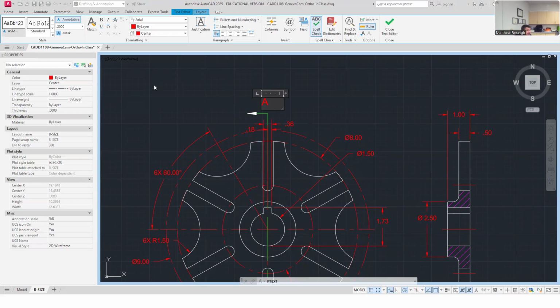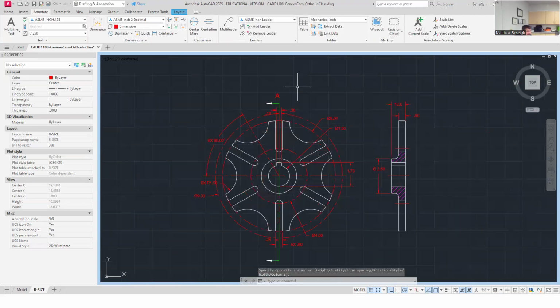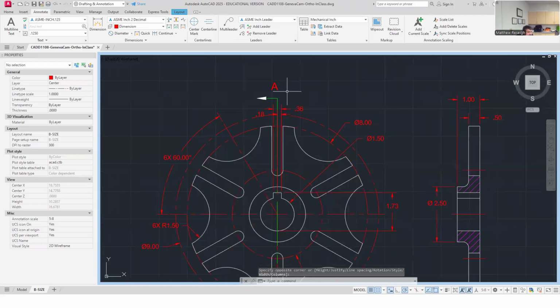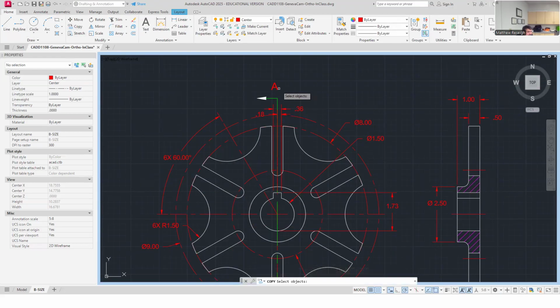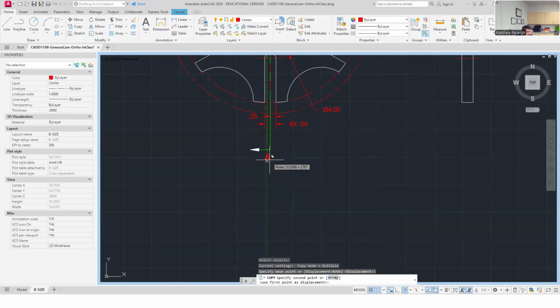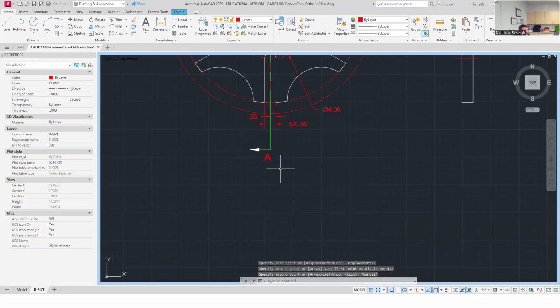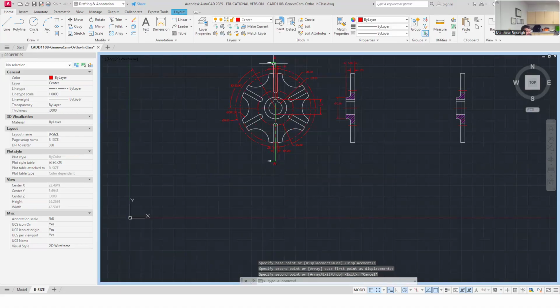We label our cutting planes with letters in mechanical. So this is going to be an A, and then I'm going to make a copy of this, because I need it to be from one point to another point. So I'm going to say it's from A to A. These can go either on the side or in front. It's not real critical. They'll just be close to where the corner turns, where I turn that corner to show. So that's an A to A section.